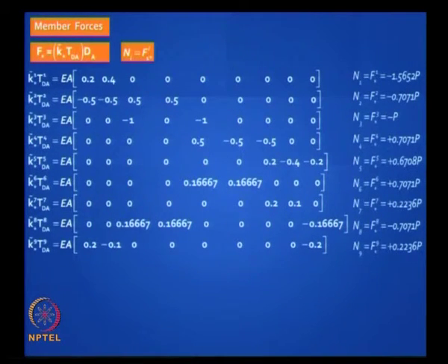That is your proof. The proof is you are checking with the force method and seeing whether you are getting the answers. So that is it, we have solved a problem that is easier to solve using the force method by the more difficult stiffness method, because the computer, the software will always do it by the stiffness method. So at least the method you are clear with while solving plane trusses.